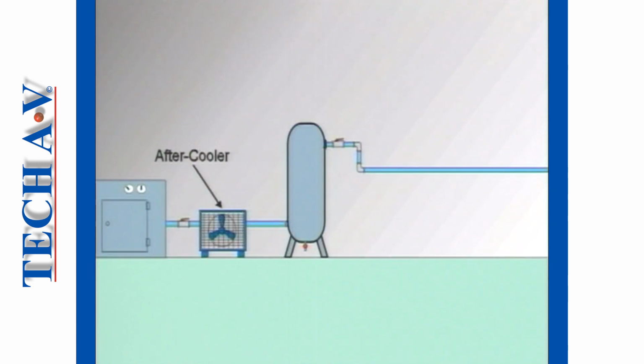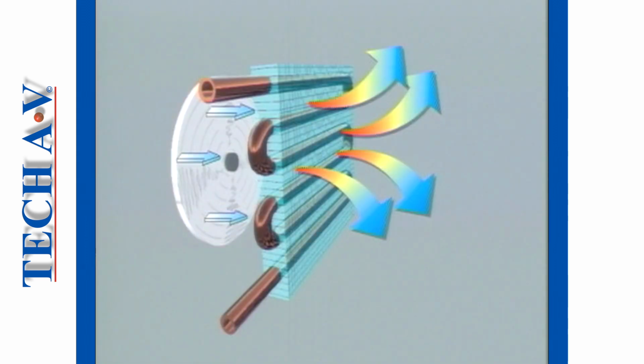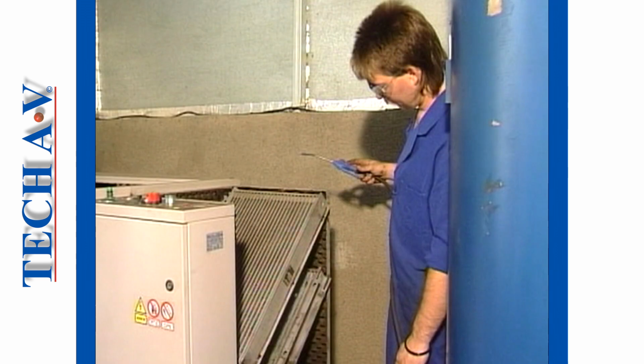First, the air needs to be cooled, as this will cause the moisture to condense. The cooling of compressed air can be done in an aftercooler, normally positioned directly after the compressor. A popular aftercooler is an air-cooled device consisting of a heat exchanger and a fan. In the case of most wet screw compressors, this is built into the compressor unit assembly.